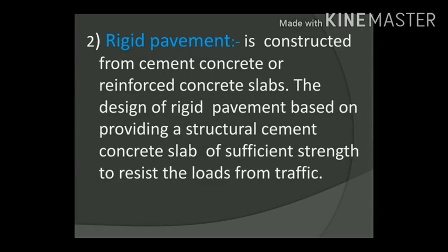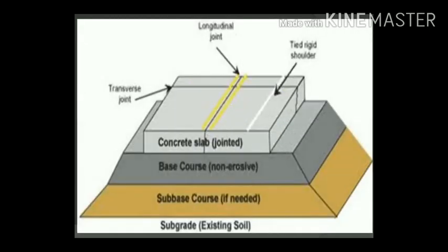It is constructed from cement concrete or reinforced concrete slab. The design of rigid pavement is based on providing a structural cement concrete slab of sufficient strength to resist the loads from traffic. The following are the images of rigid pavements.